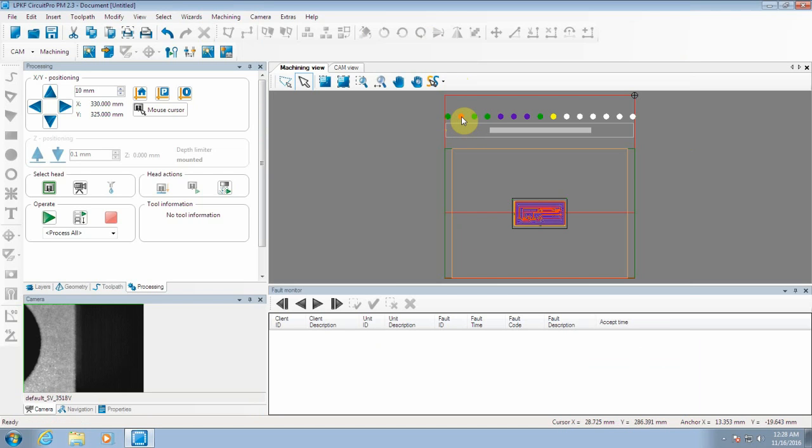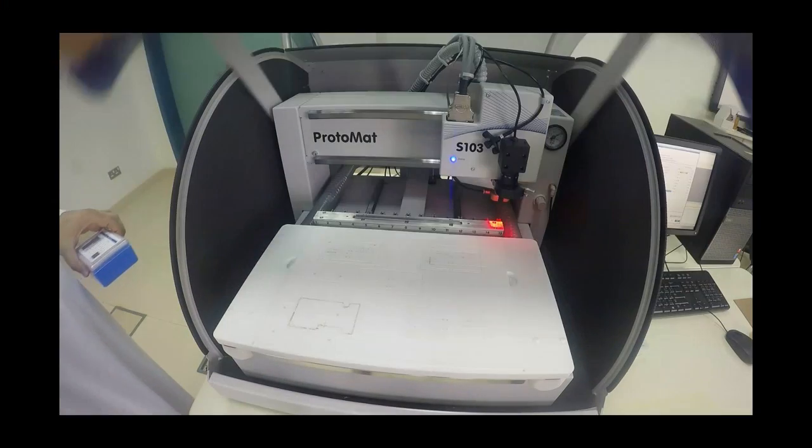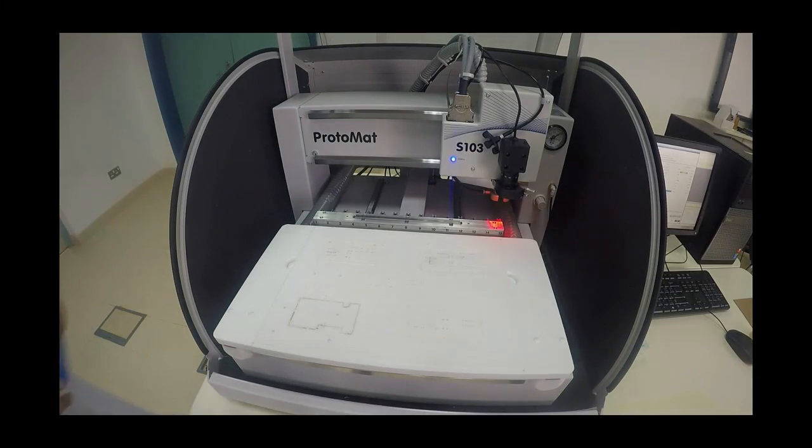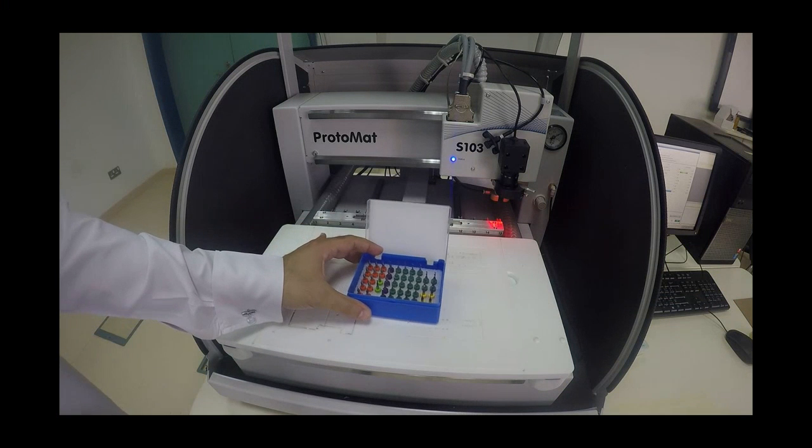The machining view shows the tool type installed in each holder. A white color indicates that the holder is free. Before running the board production wizard, we need to install the tools in the corresponding holders, as specified in the Tools Magazine wizard.